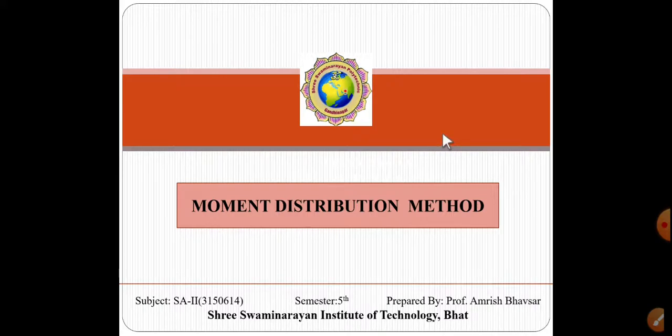So from the name of this method, moment distribution method, we can understand something. There is some moment that we have to distribute in a proper manner on the supports, as we had done in our previous method. In that method, we understood that each support gets its moment by balancing the fixed end moment. So here also we are going to do the same procedure, but with a little difference in calculation.